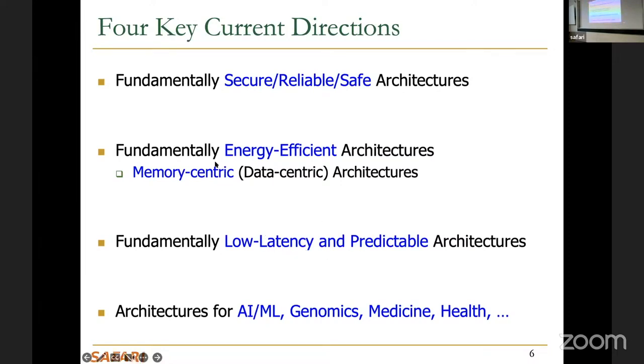Oh, before I go into it, I think, for example, this processing near memory and using memory, you can do this in all memory devices. And I'm actually quite interested in many different devices. DRAM, we've been talking about it a lot. But there's storage, SSDs, there's emerging memory technologies, and all of them have the capability to do processing using memory, some analog computation capability. And it's really good to look at how to do that and how to exploit it for applications and how to make it easily programmable. So Juan mentioned the SIMDRAM, for example. I don't remember if anyone selected that this time, but we discussed it in seminars, past incarnations of the seminar. So that takes a step towards more programmability of this analog computation in memory.